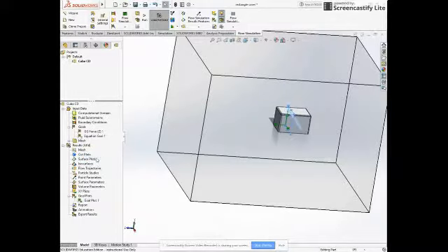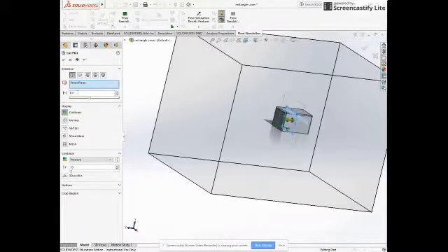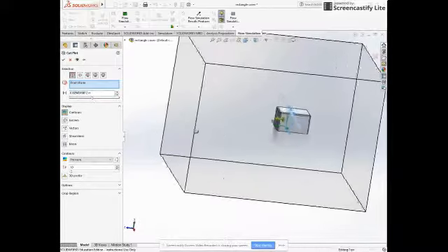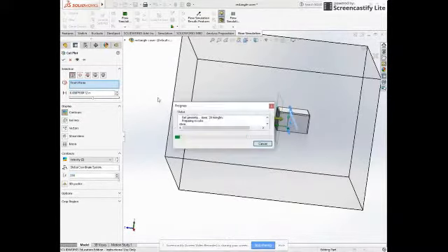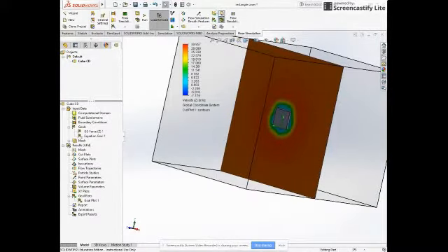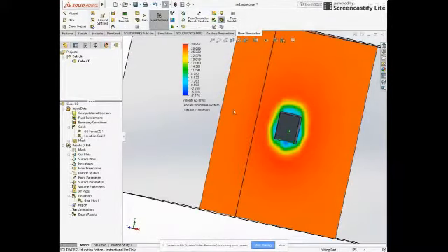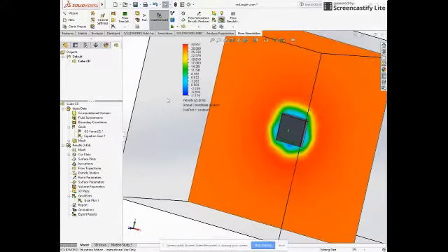That's editable. Another thing you can do here is insert a cut plot. One thing useful to do there, we'll be looking at the front face of the drone there. What we can look for is the velocity in the Z direction. That'll give us kind of a profile. We're going to want to slide the slider all the way over to the right. That will increase the resolution and hit the check mark. And as you can see now, we have a nice little profile of the velocity along the face and around the sides of this cube shell.